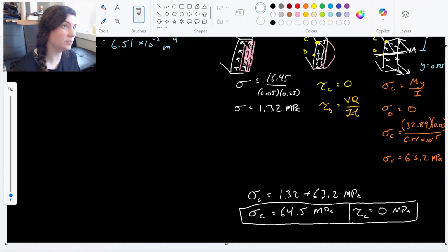All right, so we were actually able to finish out all of C, right? We applied superposition, just adding up this entire row together, right? Adding our normal stress that applies to both C and D. Add this C value for shear stress. He gets put in his own place. He's 0. And then the bending stress at C.